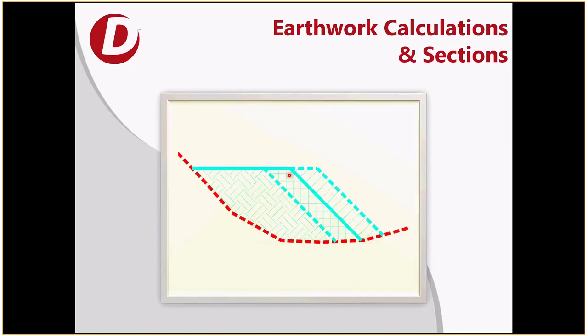If it's a heavily consolidated material, it's pretty rare, but sometimes the material actually swells in the embankment condition. And these shrink swell factors can also be fairly significant, up to 5 and sometimes in extreme cases 10%. So they do have an effect on your volume. So these are applied inside Civil 3D.